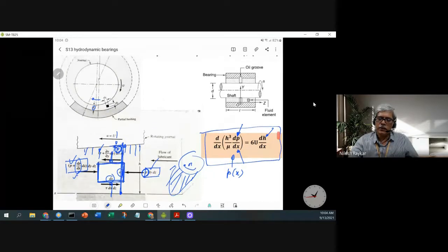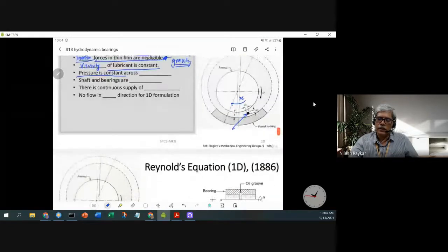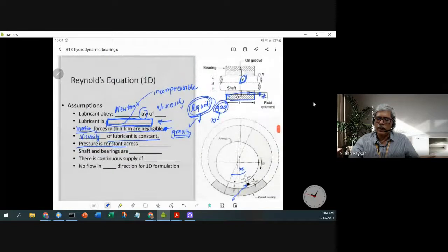As you can see here, the sleeve is open to the atmosphere at both ends. So the pressure there has to be equal to the atmospheric pressure. So towards the end, the pressure would not be the same as that at the edges in the wedge.